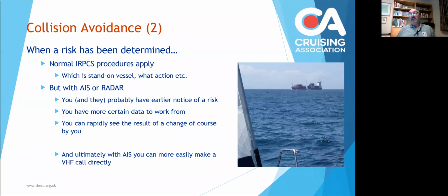Also with AIS and radar, you can rapidly see the results of a change of course by you. And of course, ultimately with AIS, you can more easily make a VHF call to that ship because you know the MMSI number, you know the ship's name. Now, many people will say you shouldn't do that, but on the rare occasions when I've called up a ship, they've been quite happy to chat and say what they're going to do about it and maybe discuss the weather or whatever.